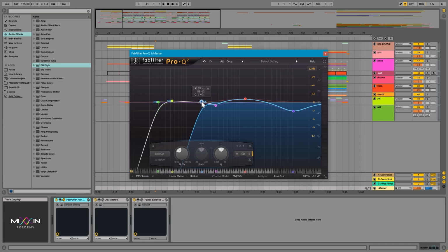And second, many sound systems that you could reproduce your music from would have everything in mono, which means that having anything stereo below a certain frequency point, and then you add those together, you would have some phase cancellation. Because what is stereo? Well, having something different in the phase on both left and the right channel, and if you had that below a certain point, those would cancel each other out. Now, sometimes it might turn out good, might turn out bad, you never know, but just to be sure that your music is going to reproduce well everywhere, you need to make sure that those kinds of technical things are taken care of in advance.